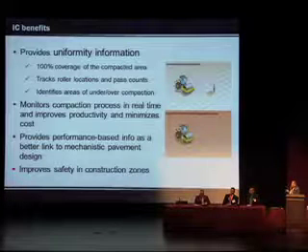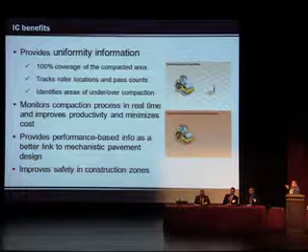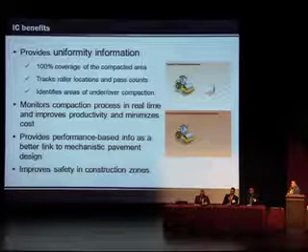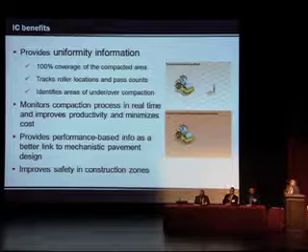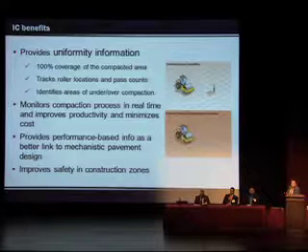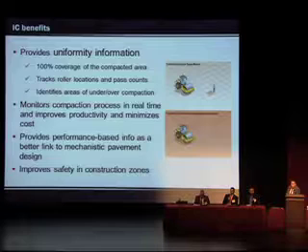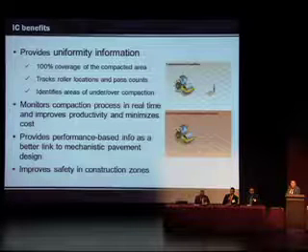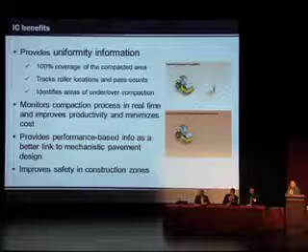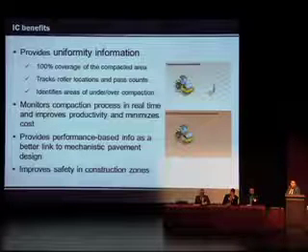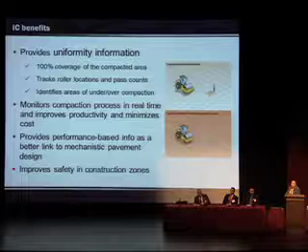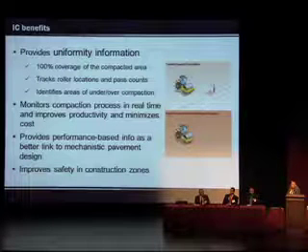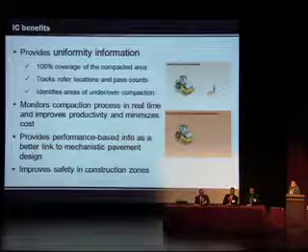Last but not least, IC also improves safety in the construction zone by reducing the staff working in the field doing spot checks. Eventually, I hope we can get rid of the nuclear density gauge or any other spot check, like a DCP or LWD, whatever test. That's a spot check. So I hope we can get there.